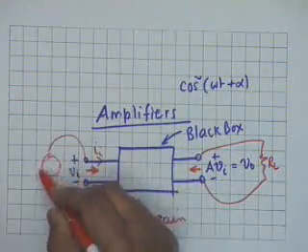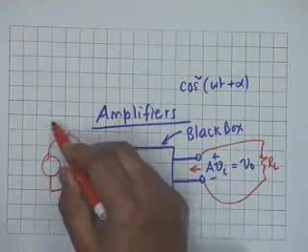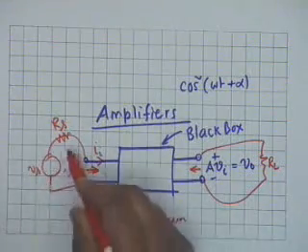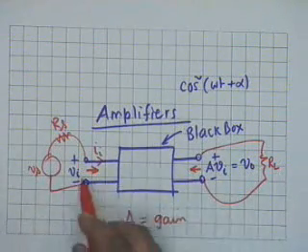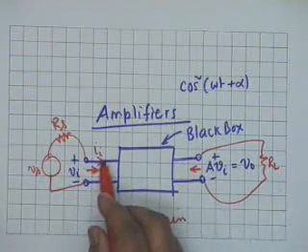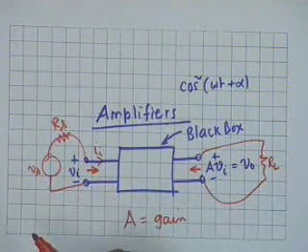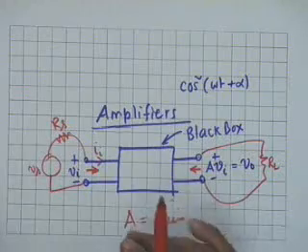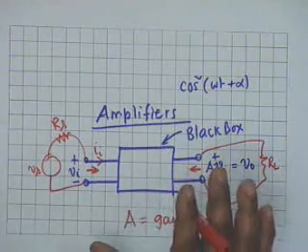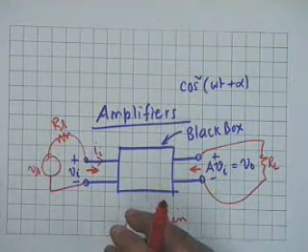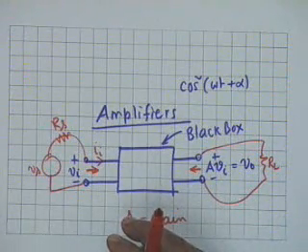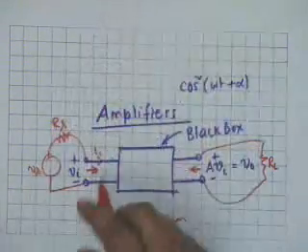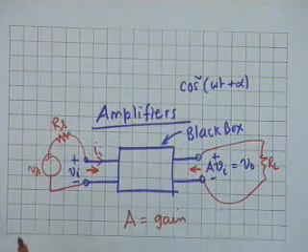That is, if you connect a source here, let's say Vs, with an internal resistance Rs, alright, the current taken here is 0, then what would Vi be equal to? Vi should be equal to Vs, isn't that right? So an ideal amplifier disregards the internal resistance of the source. It has no respect for the internal resistance of the source. Whatever the internal resistance, it develops a voltage equal to the voltage that you wish to amplify.